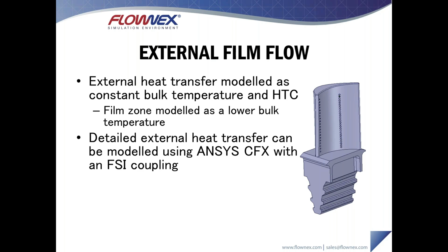Just as a note, for the external film flow, just for this webinar, I'm just going to be using fixed bulk temperatures for the flow around it with a reduced bulk temperature for the flow at the exits of our film coolant slots. I just made this assumption just to limit the complexity of this model so that it's easier to understand. However, it is possible to link ANSYS Mechanical and ANSYS CFX with an FSI coupling, and then Flownex couples to the codes individually.